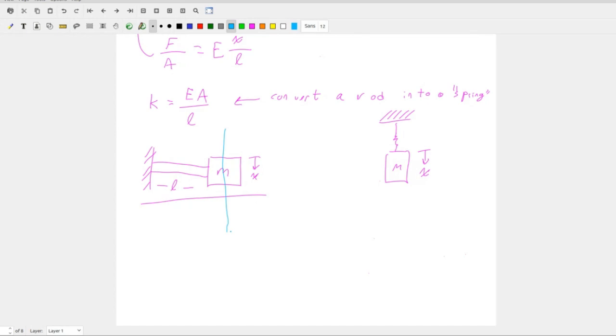So it just matters where the x is pointing, and you would position the spring to be in that same direction? Yeah, so the spring only acts in 1 direction, right? A linear spring is only going to act in tension and compression. And then it matters because if this is your engineering system, this is the direction you want to know displacement in. You're the engineer. You chose the fact that you want to know the vertical displacement. If you wanted to know the horizontal displacement, then we have a different story. You chose that, right? Your boss said, figure this out, and you said, well, I really only care about my horizontal displacement.